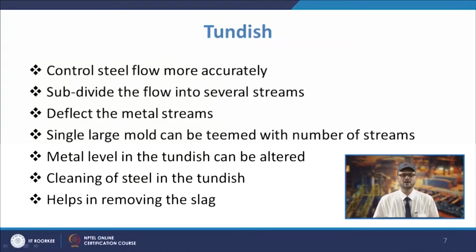Metal level in the tundish can be altered, because it is altered in the case of lateral changeover normally. Many a times in earlier days, when you have to cast different grades and you have only one tundish, in those cases you have to decrease the level of the material in the tundish, and then further you have to start filling it.